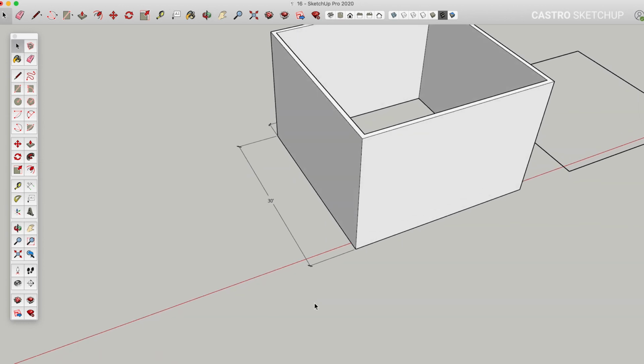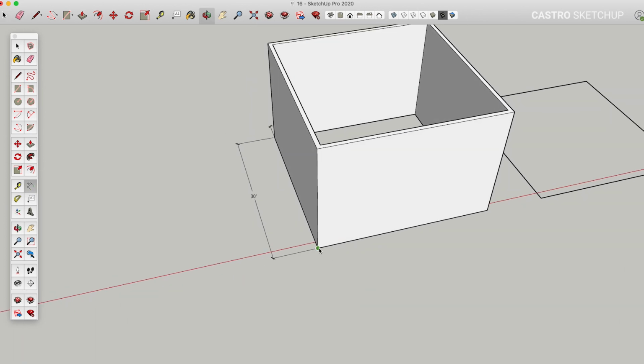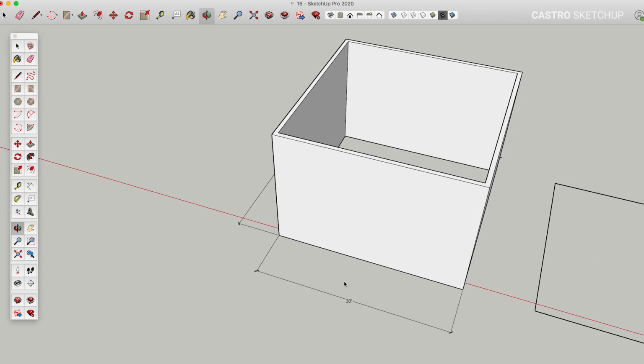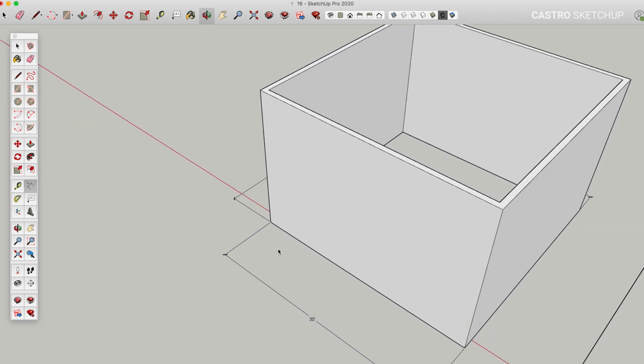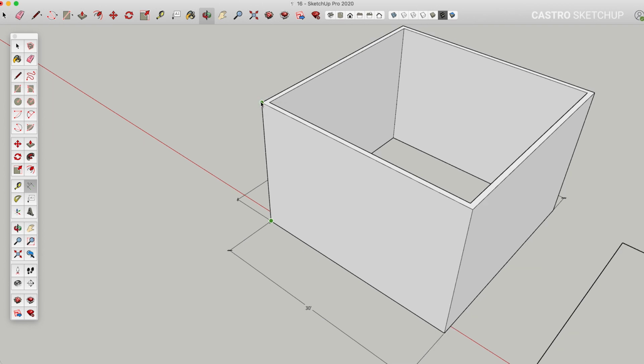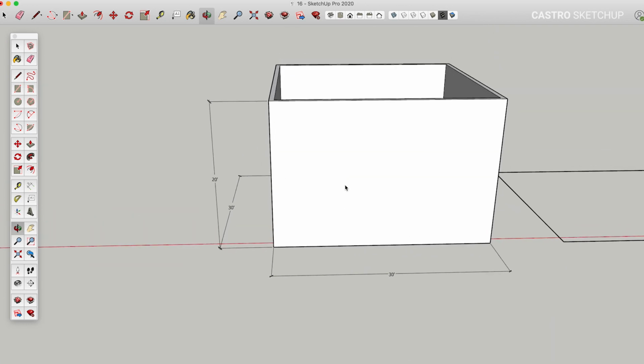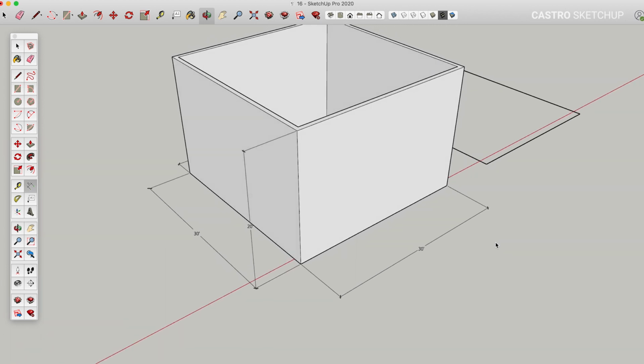There's two things here to feature. First, I'm going to start with the dimensions because that's actually what we were just going through, and you can activate that by pressing D on the keyboard as a shortcut. The way it works is you click where you want to start the measurement from, and you click where you want to end, and then you can just drag out wherever you want to have this dimension string be. So it's a 3-part process. Again, I'm going to press D for the shortcut. I'm going to click the origin of my measuring, click the second point where I want it to end, and then drag out where I want that dimension string to appear. Okay, so that's D for dimension.